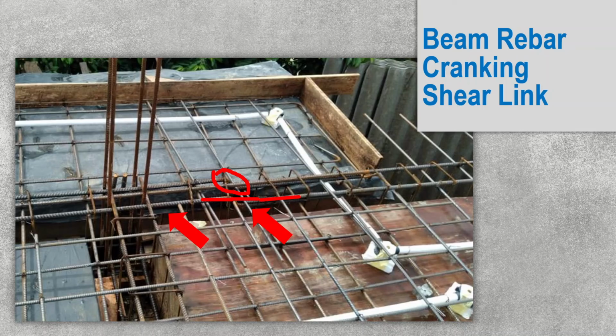If you bend reinforcement like this, there could be yielding, and it may not be able to carry any load, because when the load is applied, it could try to straighten. With that, the load carrying capacity of this beam will be reduced. Also, as you can see here, there is no shear link close to the support. So the contractor has not provided the shear link close to the support. Therefore, during the inspection we have to make sure these are provided.